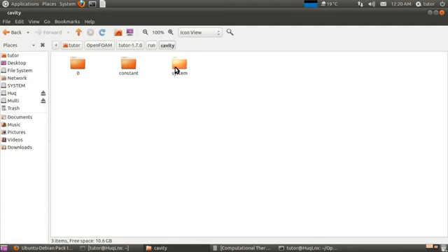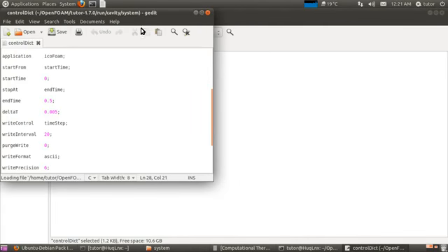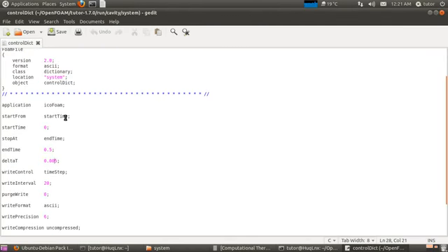And then the system folder consists of all the time information. So for example, in system there is a file controlDict which is a very important file, and the main things to see in this file are startTime, so it starts at 0, and endTime, so maybe at 0.5 with a deltaT of 0.005.